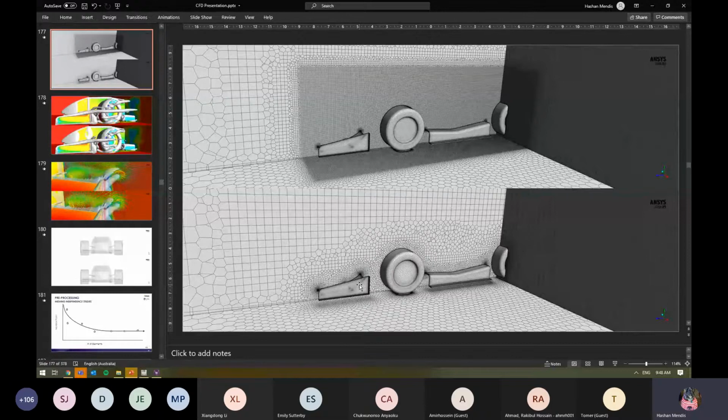And then capturing the curvature, again, you might want to start with something relatively coarse, and I'd probably start focusing around the actual surface mesh, right? Progressively making the surface mesh finer and finer, just picking up things like forces. And maybe in that particular case, you're looking at what the CP is around the wing, and how that might be changing, right?